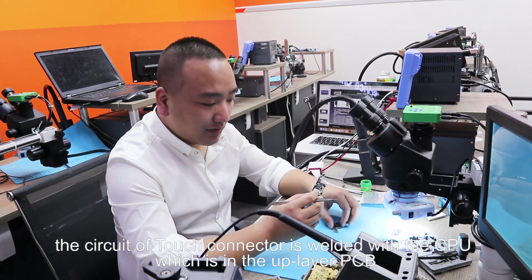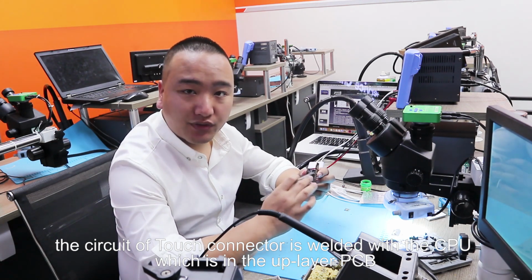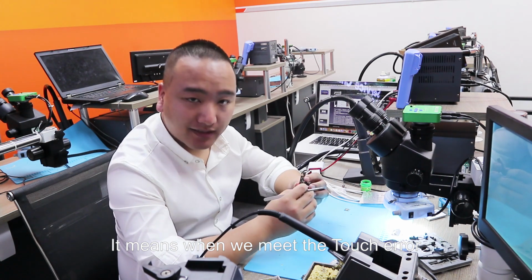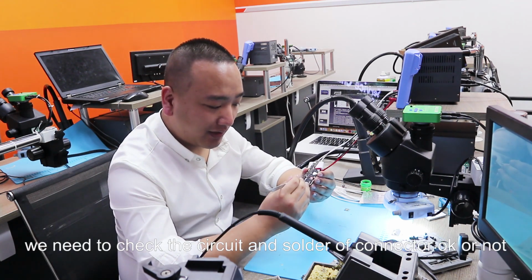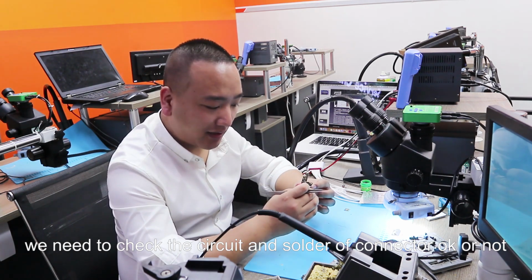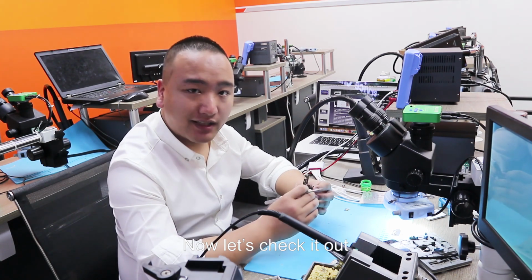The circuit of the touch connector is welded with the CPU, which is in the up layer PCB. It means when we meet a touch error, we need to check the circuit and solder of the connector, okay or not. Now, let's check it out.